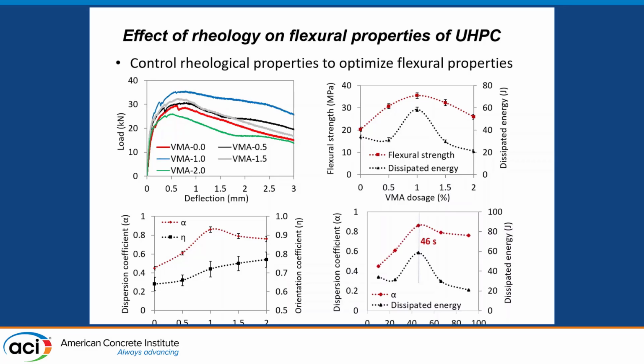And we hypothesized that if we can use the VMA at some content to control the flow time of the suspending mortar to around 46 seconds here, then we can have the best fiber dispersion coefficients, and at the same time, we can get the highest flexural properties.